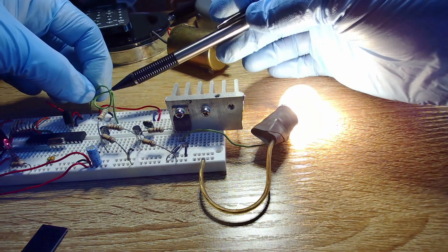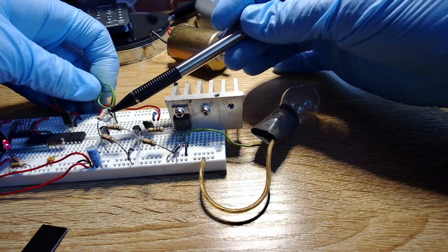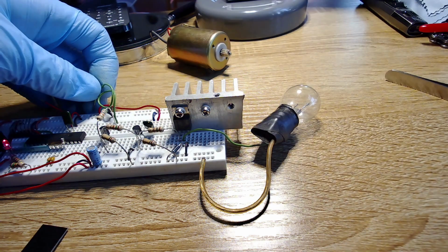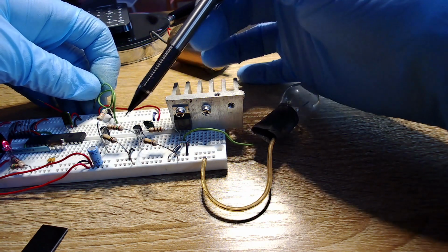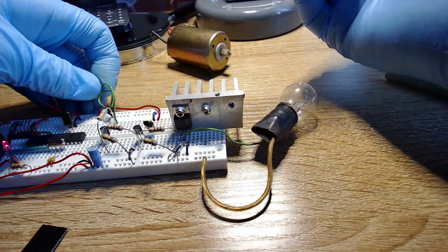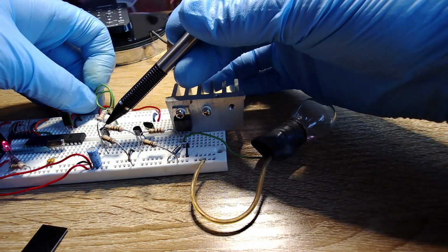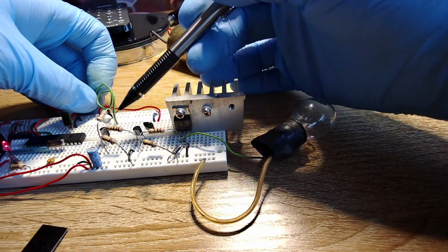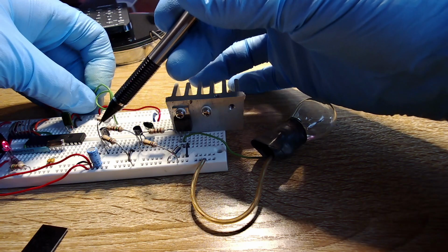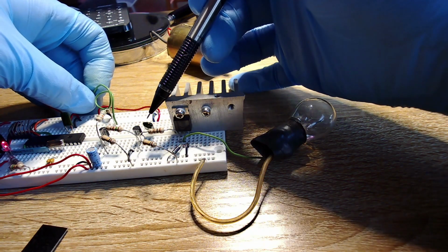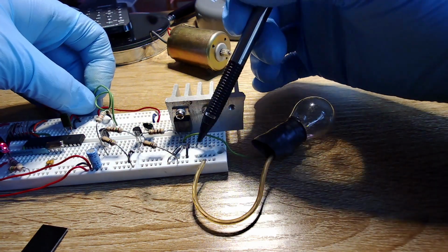So clearly, the current coming in through this wire is not powering this. The current coming through this wire is really just biasing this transistor. And I have a drawing, so I'll get to the drawing in a second. But these transistors are in a simple grounded emitter configuration, so their output is an inverted output at the collector. I will get to that on the drawing. Basically, these are two inverters. Together, they're just sending the signal without inversion to the MOSFET, which is ultimately grounding the light bulb.